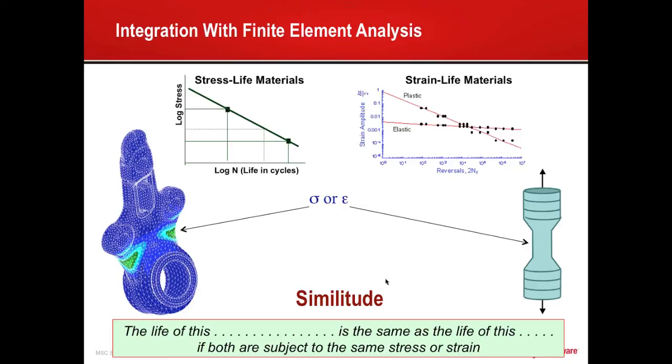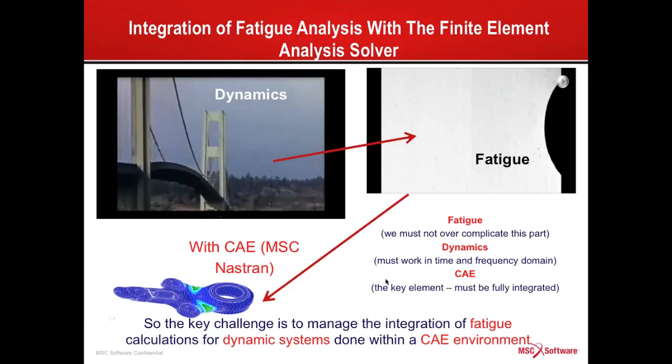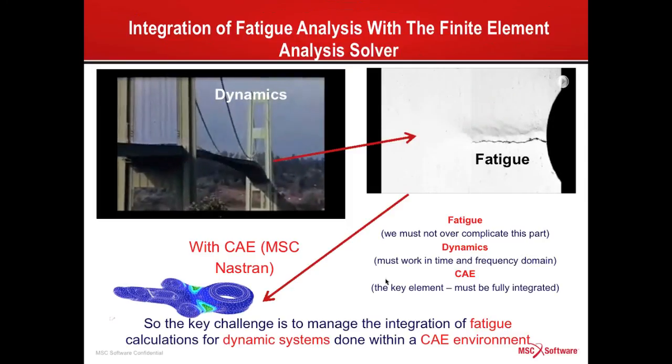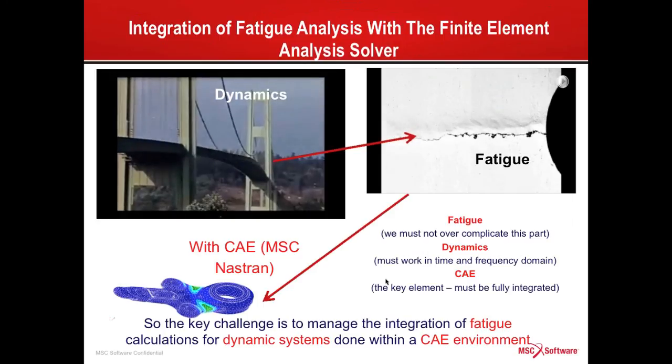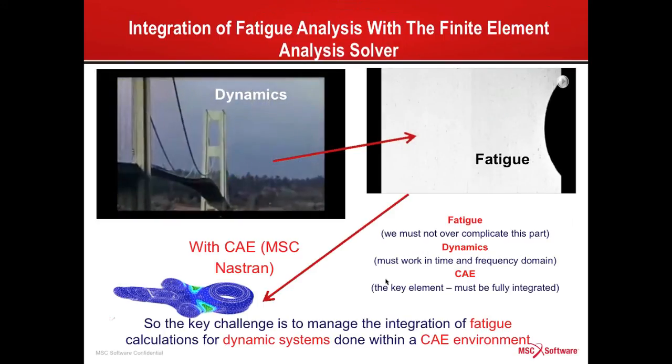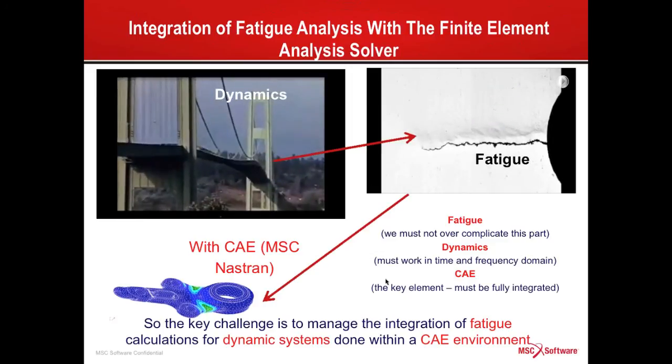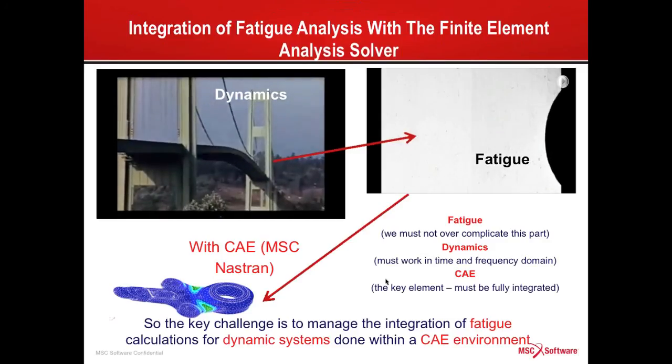We also have another big issue to deal with, and that is the issue of potential structural dynamic response. So if you've got a structure which is going to behave differently under time-varying load than it does under static load, then you need a way to incorporate dynamic behavior. And again, the good commercial codes will enable you to do this. They'll enable you to do it both in the time domain with a transient dynamic type of calculation, or indeed in the frequency domain, although that is much more of a challenge for some of the commercial codes.